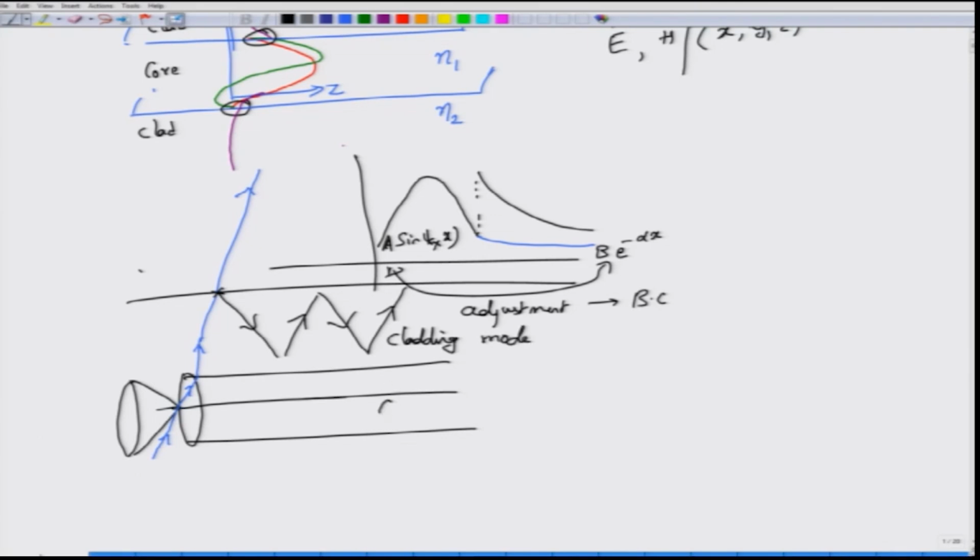Okay. What propagates inside the core will of course be core modes, or modes inside a core, and there is actually a coupling between the cladding mode and the core mode. So if by any chance I have excited the cladding modes, then these cladding modes will also propagate along with the core mode, of course at different group velocities, owing to the fact that the refractive indices are different and the propagation constants are different, but nevertheless they will start to exchange some power, okay, which means that the power in the actual core mode will be stripped off into the cladding mode. So you see that there is actually a power loss in the core mode. So for that reason it is necessary not to excite any cladding modes, okay.